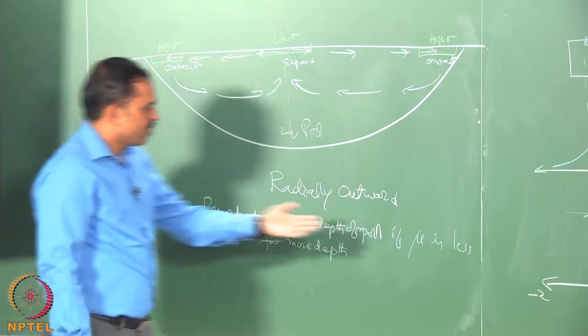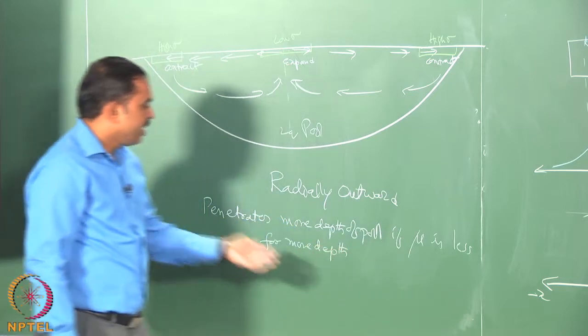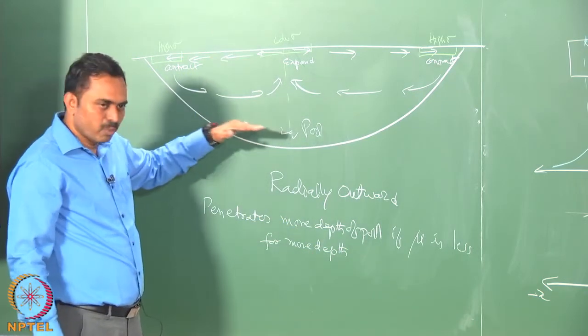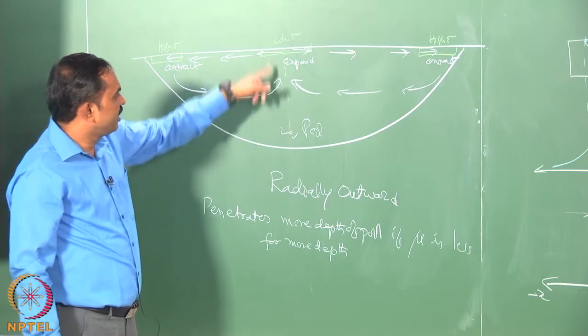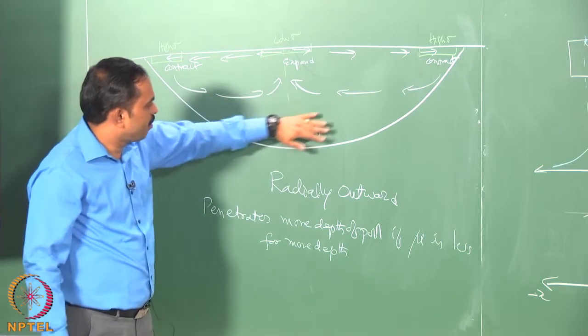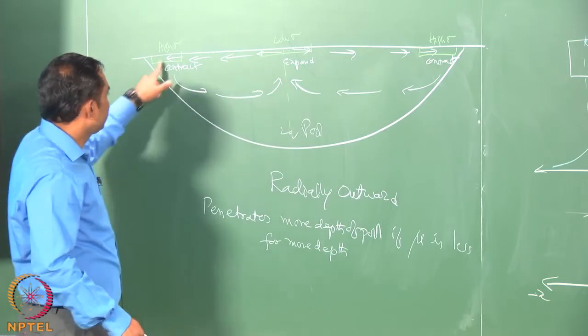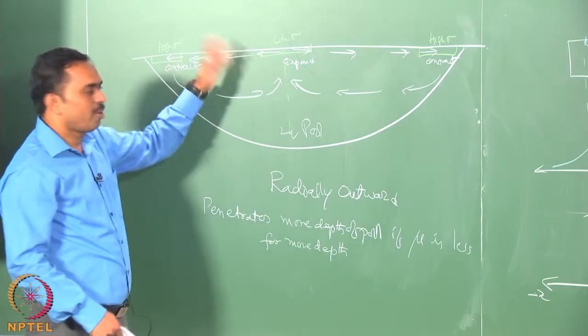And in the case where the viscosity is a strong function of temperature, it means that at high temperature it is less viscous, and at low temperature it is more viscous, which means there is a viscosity gradient upward. That means that the liquid at the bottom is very viscous and cannot be moved easily. So, this surface convection will be limited to the top layer.